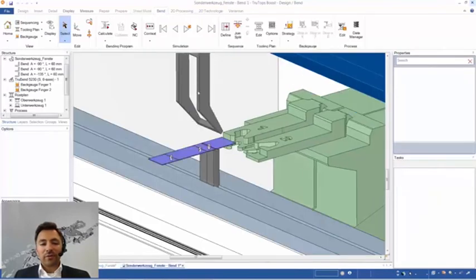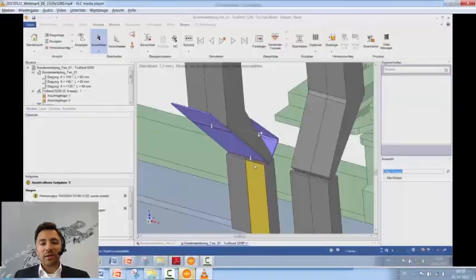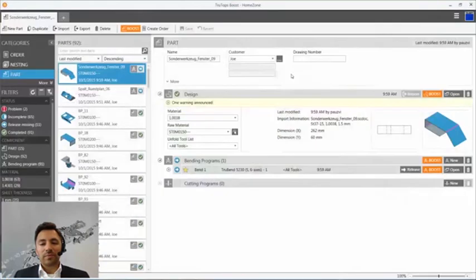How to generate that tool? You start the data manager, go into your dice, copy the existing tool, and right-click on your copy tool and edit it within the design level. And basically, you can create any tool which you, of course, have physically, and you can simulate, of course, the result within Bend.